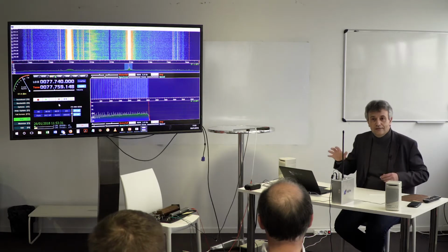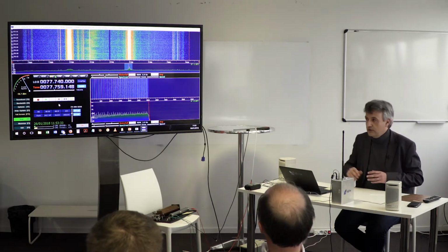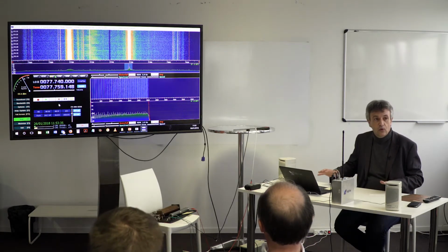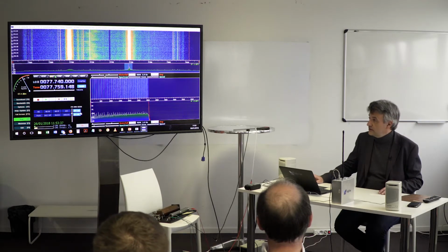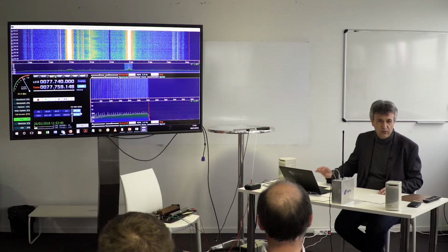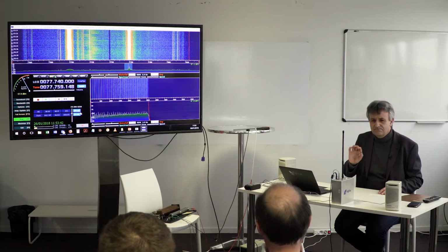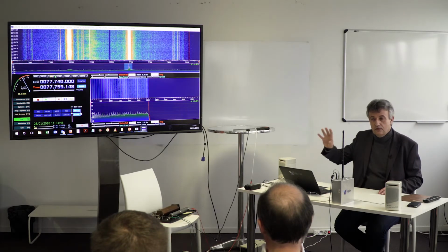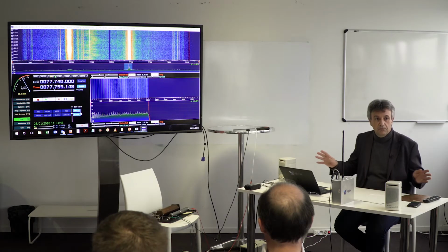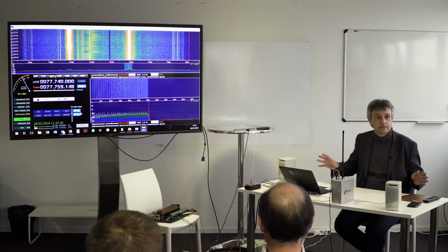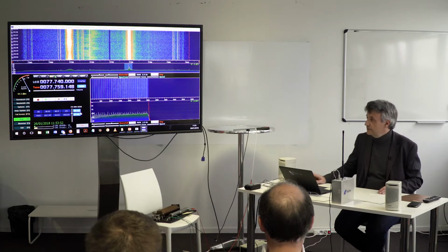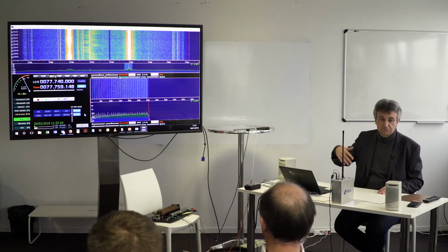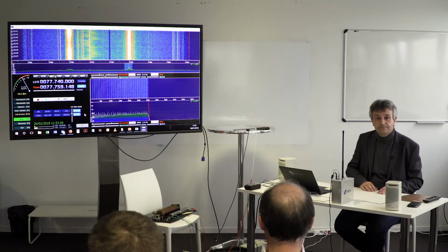It's almost quiet, except this 50 hertz and 100 hertz noise. So we came from a situation where we were really only detecting the presence of the signal in FM mode to a situation where we are in what we call the quiet condition. So basically gaining 20 dB or more just by tuning the antenna. Okay?